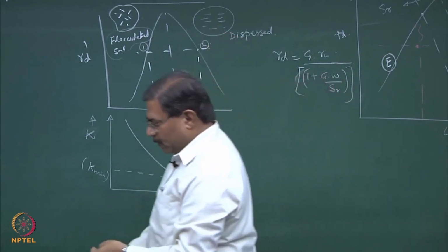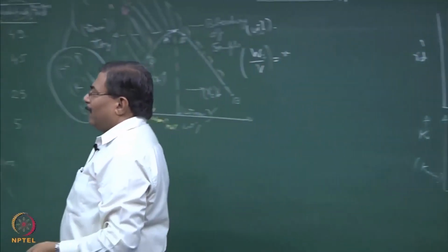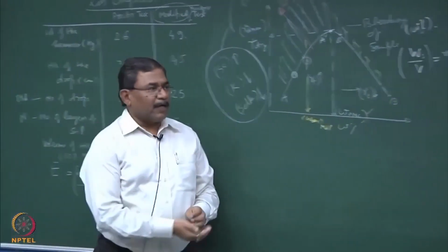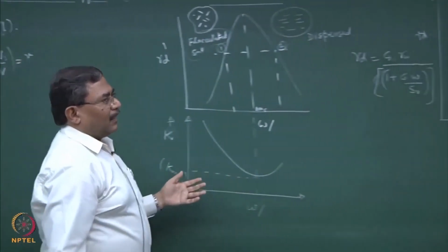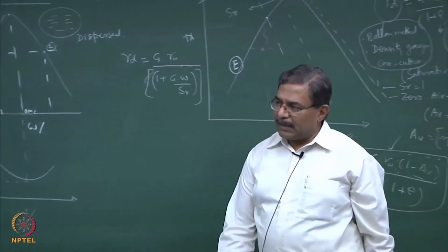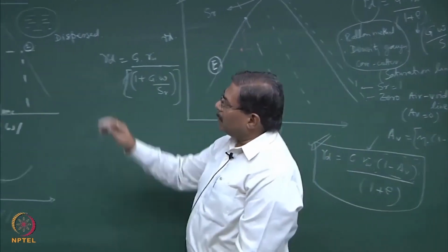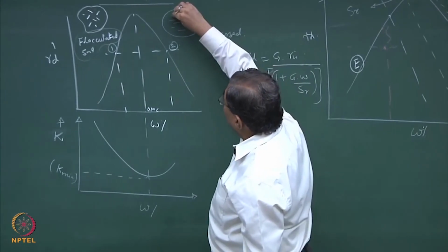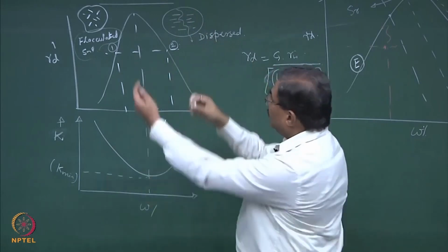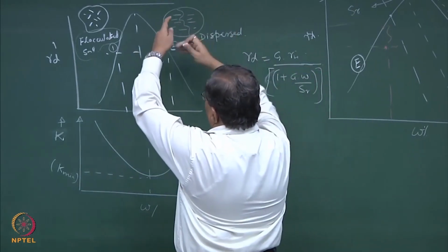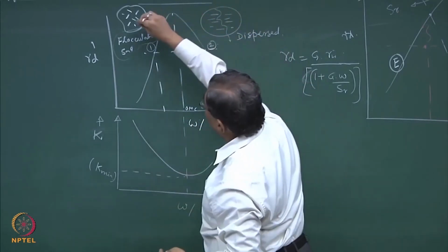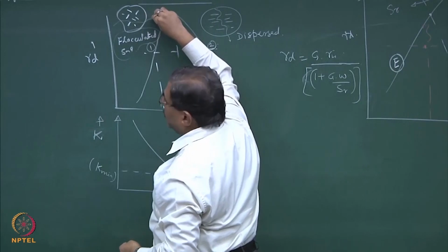So, if I was a petroleum geophysicist and if I do an exploration in the middle of the sea and if I get samples of soils which are totally dispersed, I have wasted my money in exploration, and this is how most of the wells are discarded, because a dispersed structure is not going to allow the permeation of the fluid so easily. It is going to be very zigzag. There is a lot of hindrance which the particles are going to create for the movement of the fluid as compared to this system where the fluid movement could be easier.